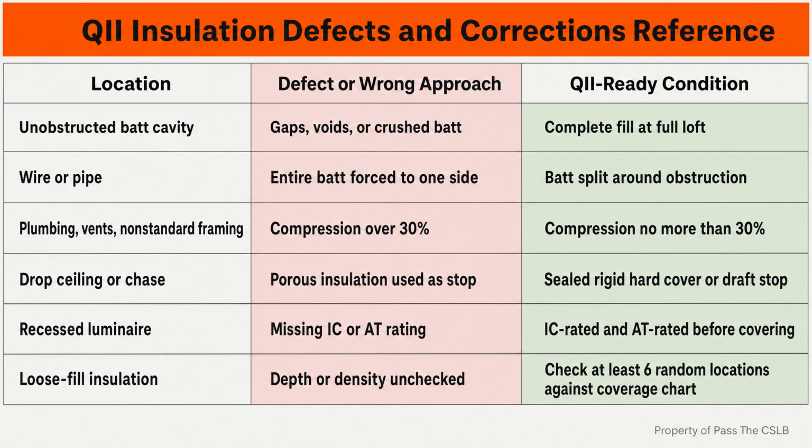Several special locations deserve a deliberate pause during the walk. At a tub or another large fixture placed against an exterior wall, the sequence must preserve the required cavity boundary. If the fixture blocks later access, the suitable, rigid barrier and related insulation detail need to be completed at the proper stage rather than improvised from above after the fixture is set.